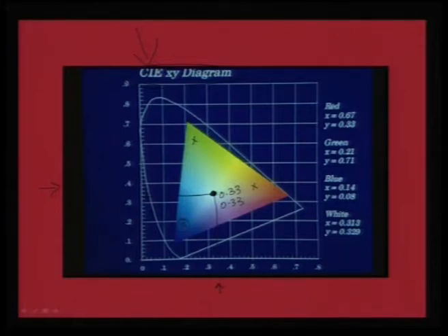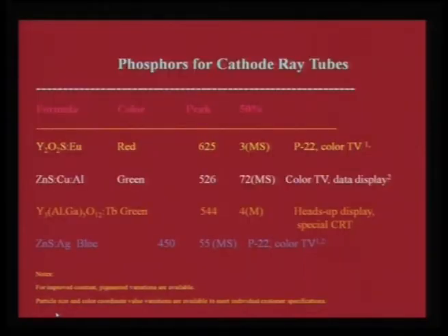So, this is a very useful parameter to evaluate what sort of a phosphor you make. Whenever you make a phosphor and you see there is a potential, then necessarily you need to talk about CIE coordinates, then the color purity is actually defined. Typically these oxides which are used are colorless in ordinary light, but in the presence of UV radiation you would see that they are glowing, and in cathodoluminescence this will become much brighter, therefore it will give a dominant green, blue and red.